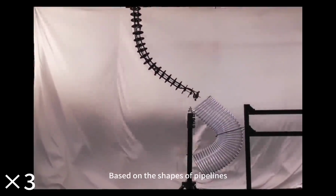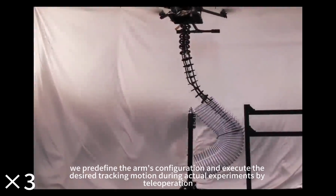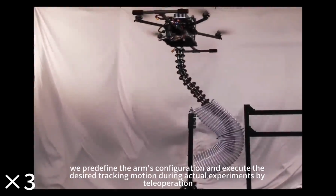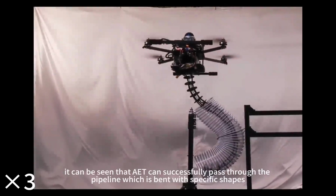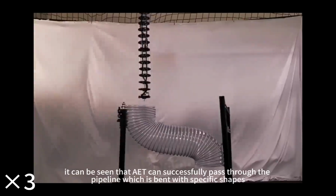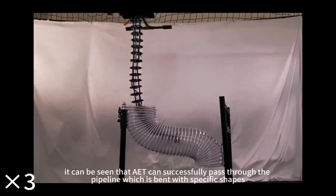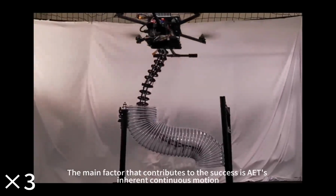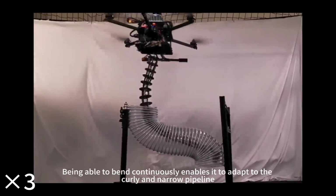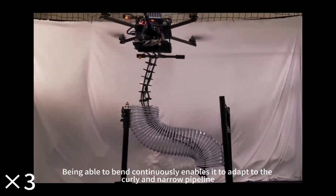Based on the shapes of the pipelines, we predefine the arm's configuration and execute the desired tracking motion during actual experiments by teleoperation. In the experiments, it can be seen that AET can successfully pass through the pipeline, which is bent with specific shapes. The main factor that contributes to the success is AET's inherent continuous motion. Being able to bend continuously enables it to adapt to the curly and narrow pipeline.